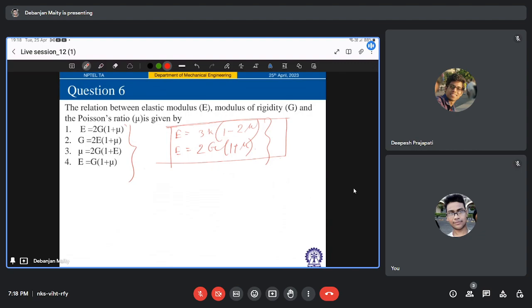What I see many a time is that we require a high amount of ductility in the structural member, right? Because having that property, it will accommodate some permissible amount of strain, and also it will redistribute the stresses without permanent or premature fracture. So that way these properties are desired basically.